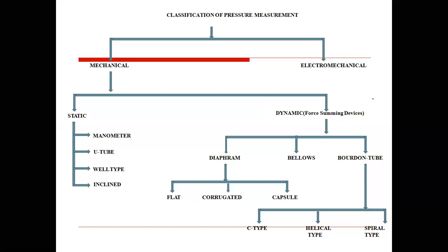Another means is pressure measurement depending upon the differential pressure, where you have a known pressure and an unknown pressure applied. So you can easily determine delta P, which is the change in the pressure. Delta P is equal to P1, which is applied at one of the legs, minus P2, applied at the other leg. P1 may be known or P2 may be known. So delta P can be easily determined depending upon the differential pressure value we are getting. Suppose P1 is known, and delta P we have obtained.